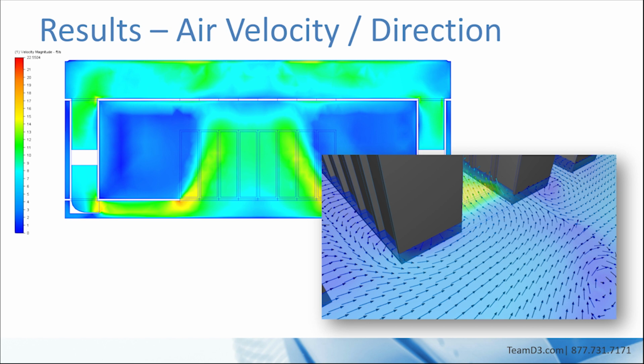Color gradients are utilized to visually indicate local velocity magnitudes. At a glance, anyone can see where the fastest air is moving. We can also see the direction of the fluid flow at any point in the domain. Vector arrows can be shown on the cut planes and are incredibly helpful for showing the dominant flow path or areas of recirculation and stagnation.